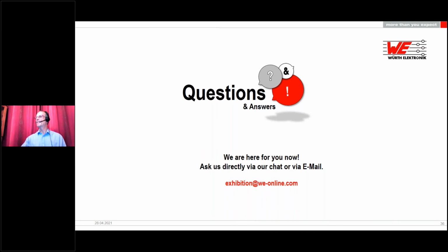Oh, you can. Okay, so the first question being, can you indicate a simple way to estimate the value of a series resistor to limit the power dissipation of the crystal, maybe in relation to the ESR? There is quite an easy, not a general rule of thumb. Generally for oscillator circuits running in the megahertz range, generally you don't need a limiting resistor. Not always, but generally.